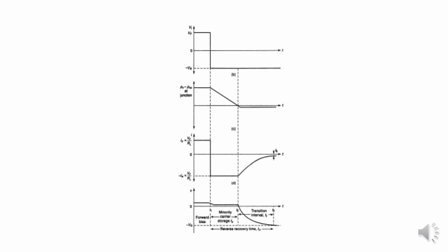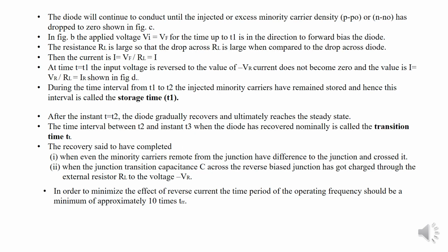And the storage and switching time can be reduced by introducing gold impurities into the junction diode by diffusion, and the gold dopant, known as the lifetime killer, increases the recombination rate and removes the stored minority carriers. This technique is used to produce the diode and other active devices for high speed applications.